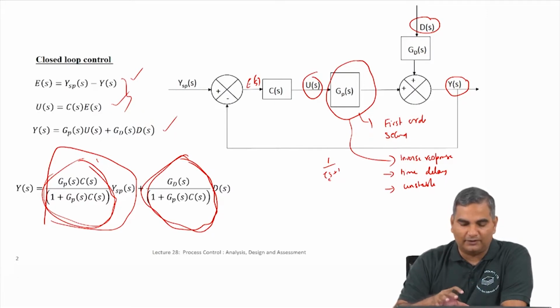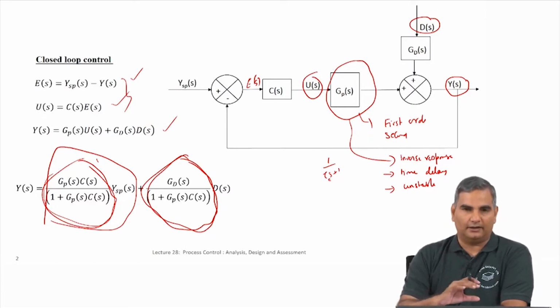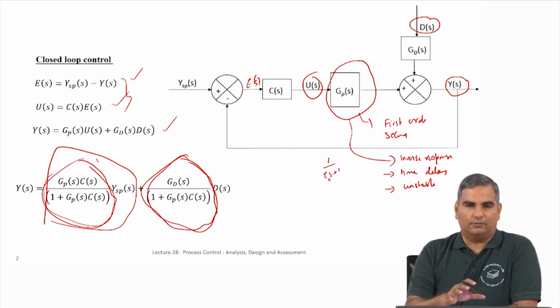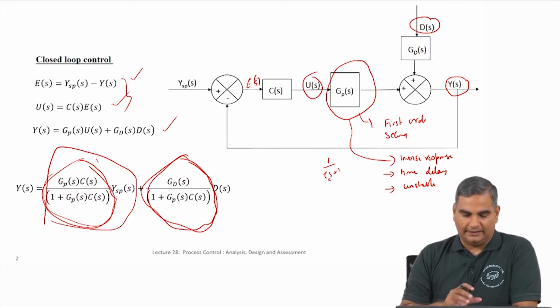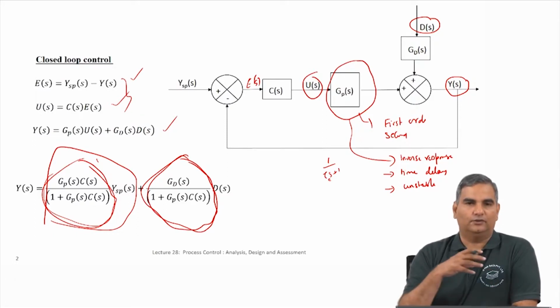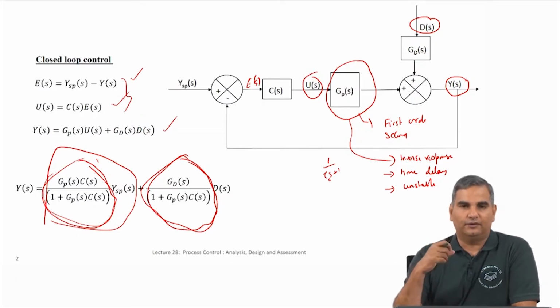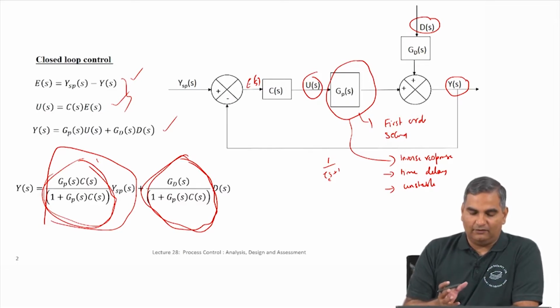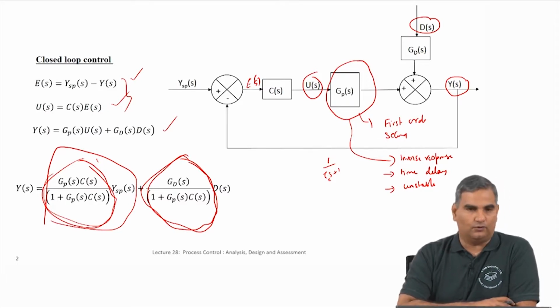So, that will be the first time we will actually look at a 2 by 2 system in a block diagram form, more fleshed out block diagram form like this in this course, and you will see how this notion of feed forward control can be thought of as a forerunner for this decoupling controller, and look at expanding the single loop to let us say 2 loops at the same time which are interacting. How do you make them interact in ways that are favorable from a control viewpoint?